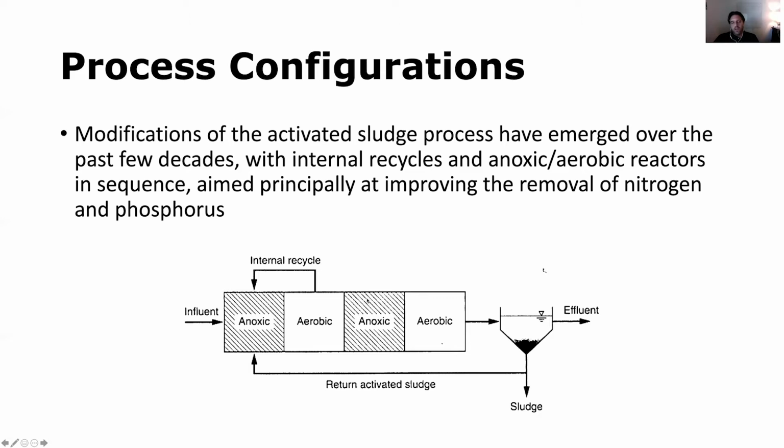And the denitrification would not work unless we added back a carbon source. In some wastewater treatment systems, they actually add methanol or a different carbon source into the anoxic reactor in order to achieve denitrification. However, in other systems, they utilize an internal recycle of the mixed liquor. Mixed liquor is what we refer to as the microbial biomass that's growing in the aeration chamber.